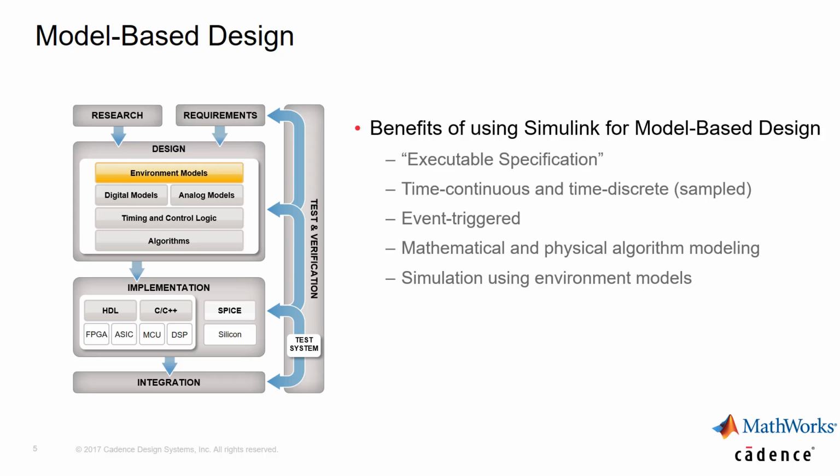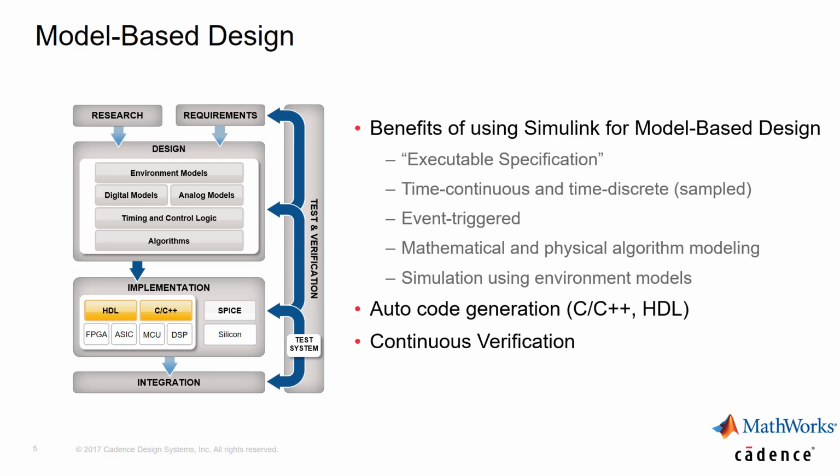Lastly, model-based design, or MBD, supports in many cases translating a system model into an implementation model through code generation, either in the form of C or C++ code or even HDL. And of course, we need to test and verify to make sure the implementation spec matches our executable specification.